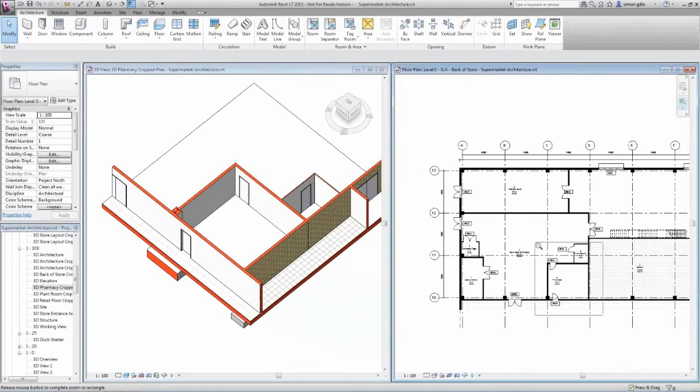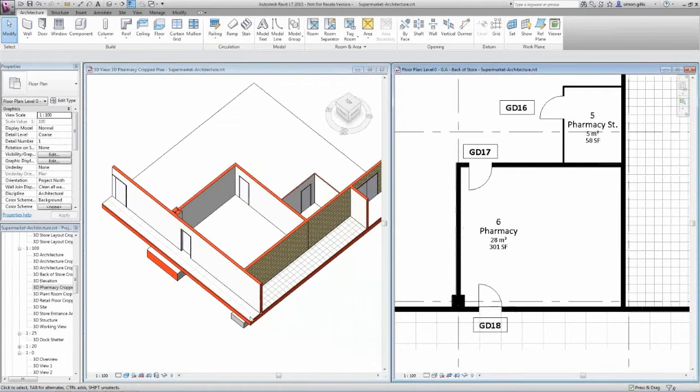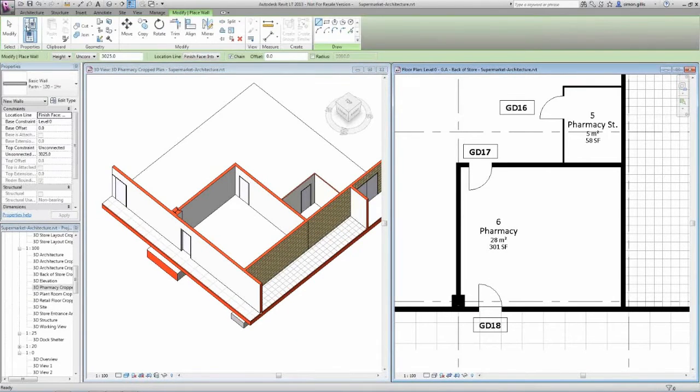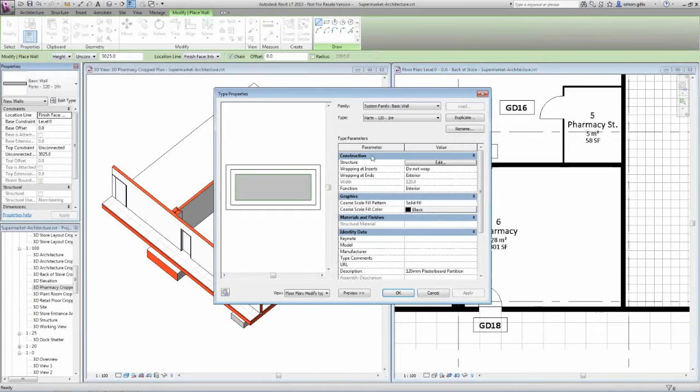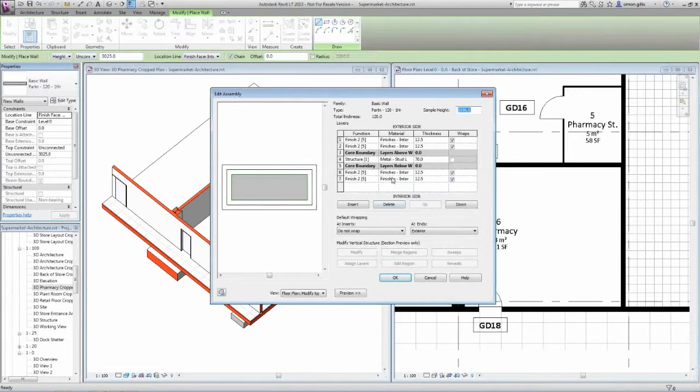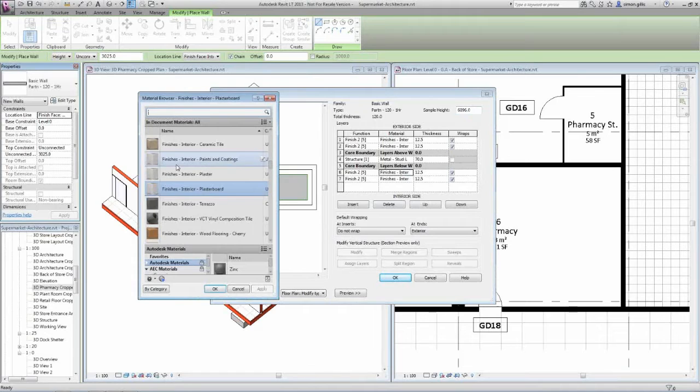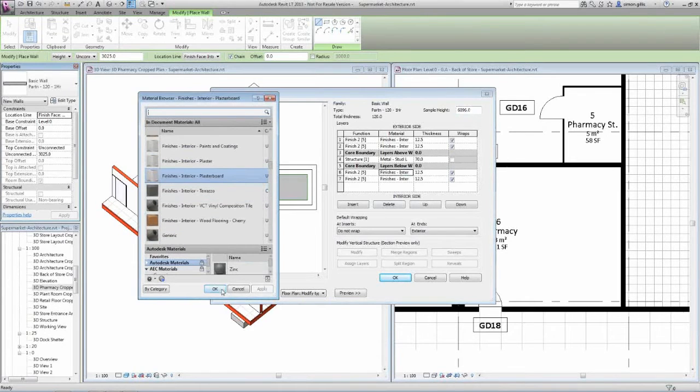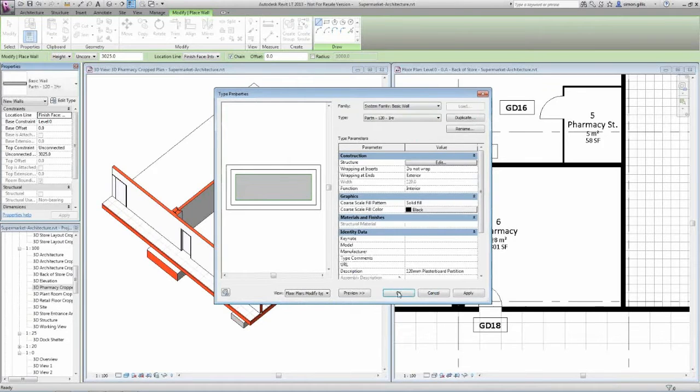Okay, what you're using with Revit is architectural components. You're designing with intelligent architectural objects. So unlike using lines, arcs, and circles, you're able here, for example, to specify a wall type. You can specify how that wall is made up, the different layers within that wall, and you can apply materials to it. And this isn't just for visualization purposes, this could also equally be for material takeoff.